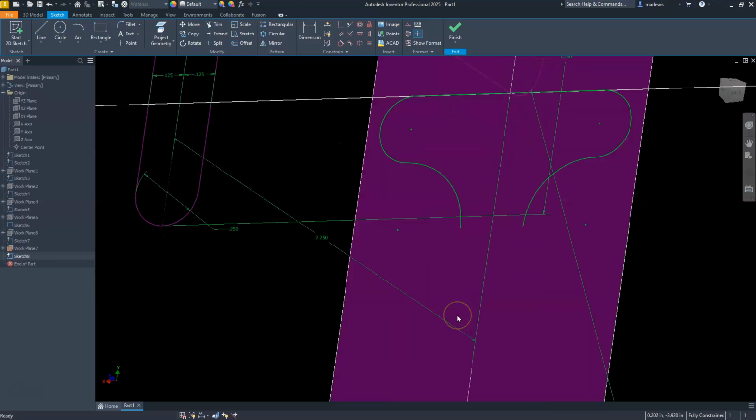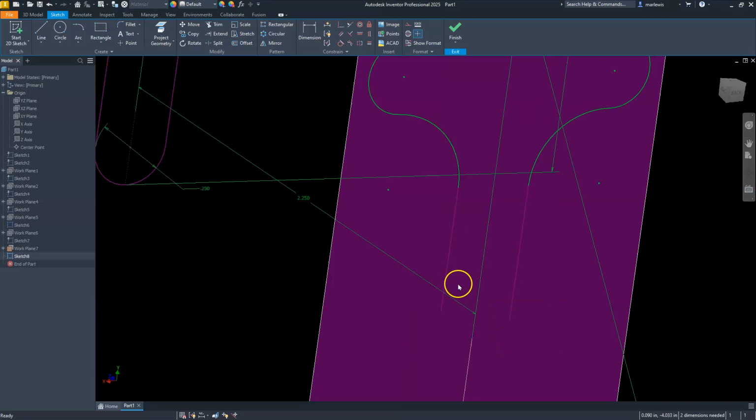This is a D one, so remember that the height is 0.75. So let's go ahead and draw a line from here, going down to here, and likewise here on the other side. All right. Let's go ahead and make both of those the same size. So I'll select an equal constraint and place them on it. See if we can get away with a tangent arc here. I kind of move that.